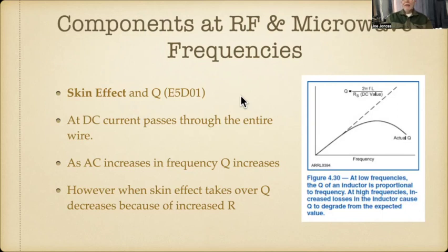And if you're at 432 megahertz trying to work moon bounce, you better have silver copper tubing for your coil in your transmitter, because all the current's going to be right out there on the surface, and none of it's going to be running inside.